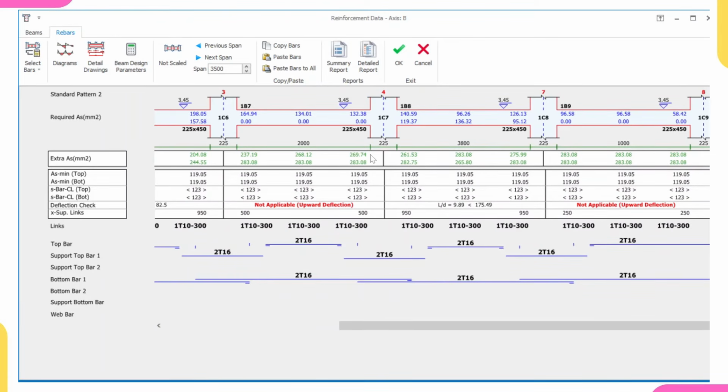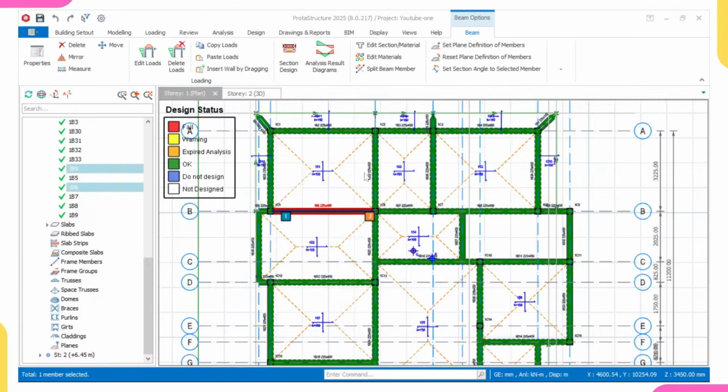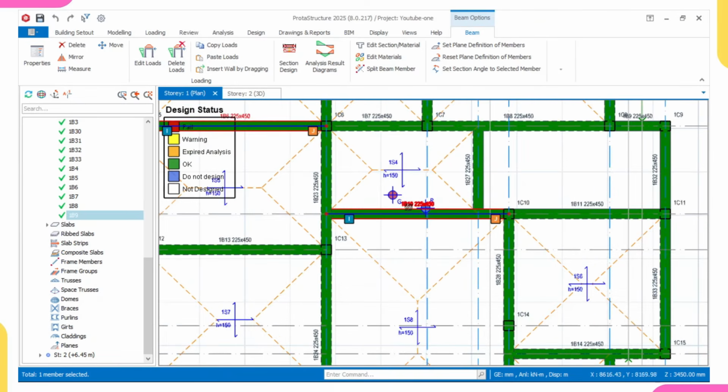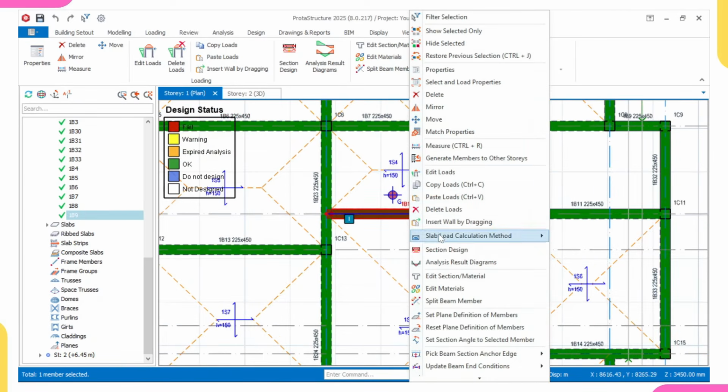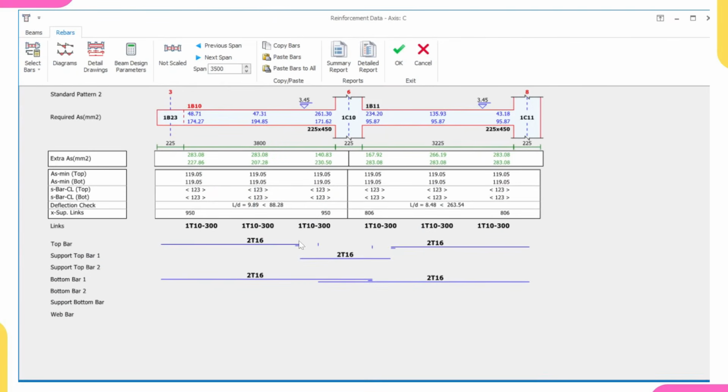It's not that the engineer did not do a job, it's just that the companies producing all this reinforcement are tampering with quality. They are not giving us the exact quality. So in order for us to prevent the collapse of the building, we will do this. Also, another thing that you can do to prevent collapse of a building is to ensure that you accurately lap your reinforcement. But we shall do that more once we come to detailing. Ensure that you accurately lap your reinforcement, in the sense that lapping length should be 50D. That's 50 times the diameter of the bar.